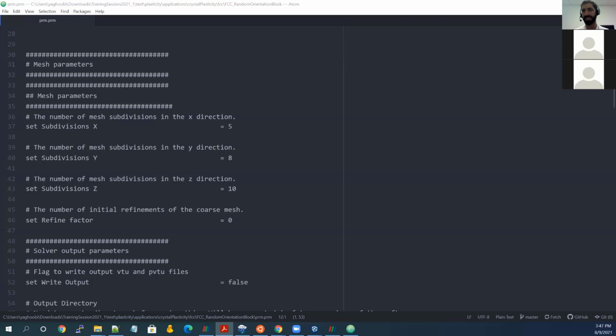But when you're reading an external mesh, imagine instead of 1, you have 0.999. Then you need to have a certain region that says, if the node is within that window of 1 plus or minus that round-off error, then it's still considered a boundary node. And that region or round-off error can be decided by this number, 0.05, multiplied by the domain size. So is this a relative factor? That's just to make sure.